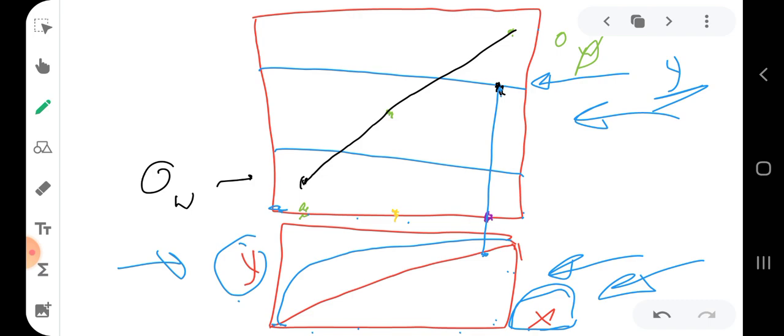So when we reach the 45-degree line, we are going to move horizontally. Why? Because when we are moving horizontally, we are moving at constant y that we know. So we can read a new value of x. See, if you move from here to here, x will change. That's why we are moving horizontally. So we keep our knowledge of y constant and we move horizontally to get the new value for x. Okay? So once you get a new value of x, we are going to go back to the